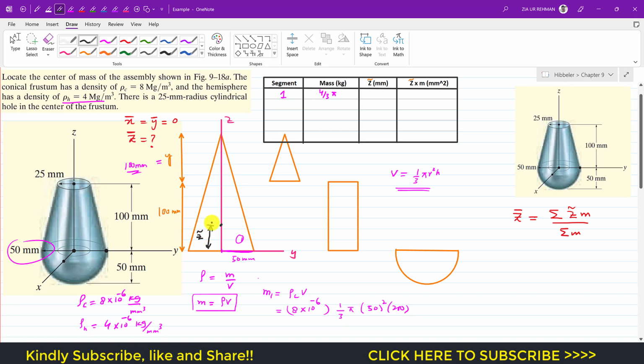And as we know, the location of the centroid of the cone is h divided by 4, that is the height divided by 4. So the height of this full cone is 200 mm, that is 100 plus 100, that is 200. So z tilde will be 200 divided by 4. If we say that z tilde 1 is the centroid location of this segment 1, it will be 200 divided by 4. So that gives us 50. This means that the centroid of this full cone is at a distance of 50 mm from this y-axis. So I will write that this is 50.